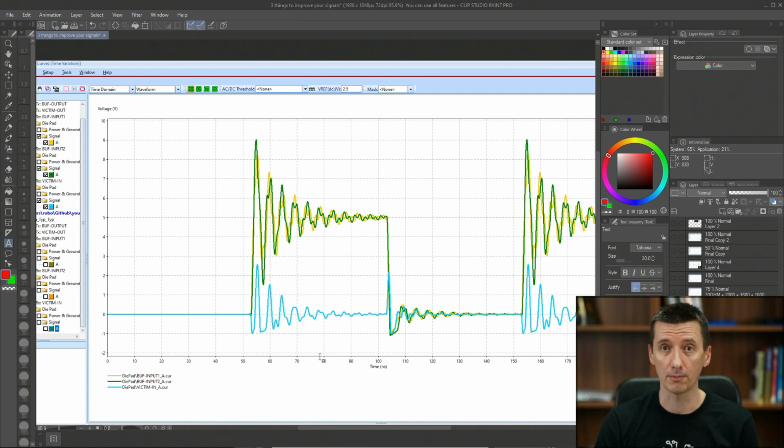If you use a cheap scope, then what you will see may look completely different, it may be completely wrong, and it may not show you what is really happening on your PCB. So don't forget, your scope may not be showing you what is really happening on your signals.